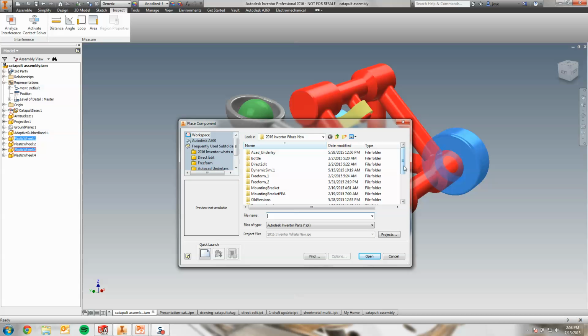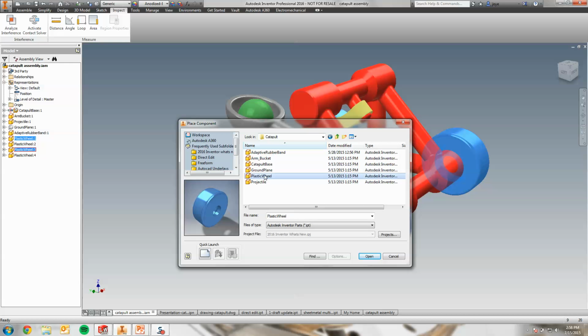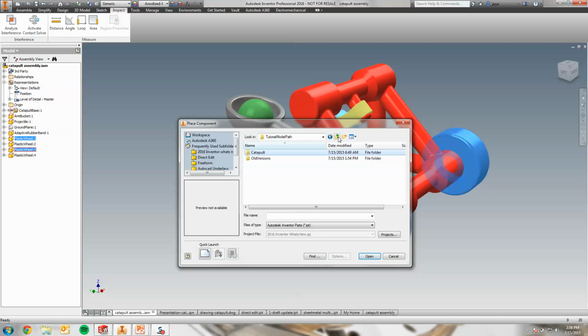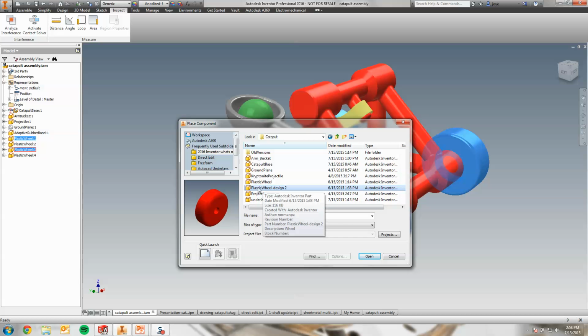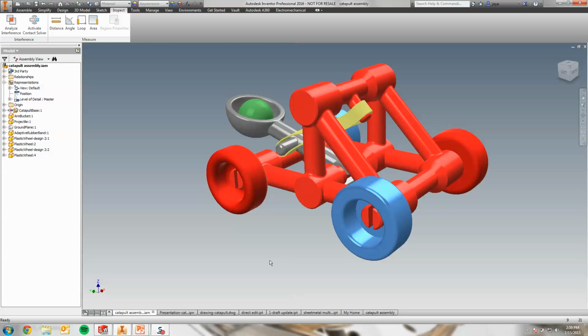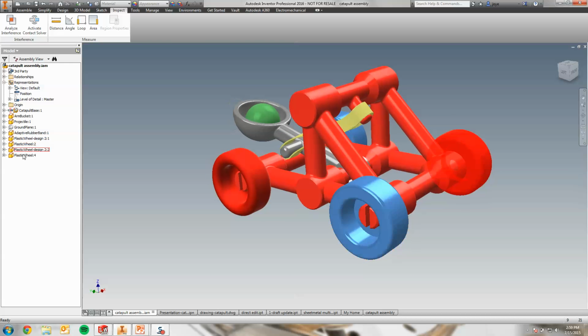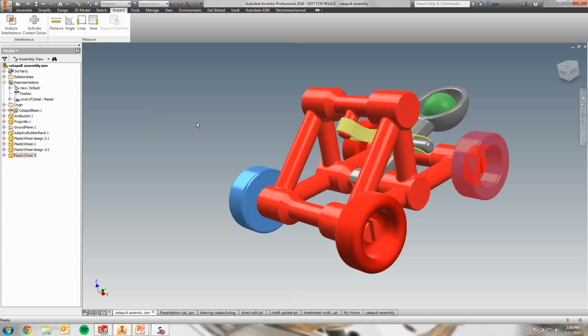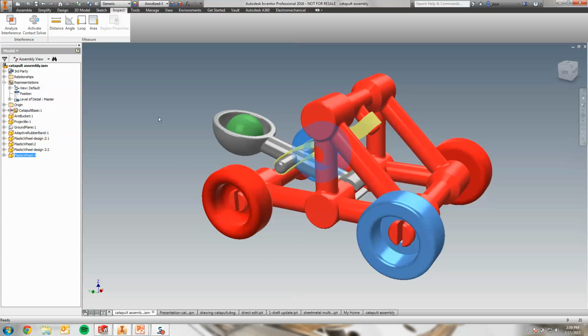Replace, and I could go into, I believe it's dynamic here, let's see here, so here's a different representation of that wheel. So I just want 2 wheels replaced with that instance there. So I just randomly selected 2 components, right clicked, did replace, and I only had to do that one time. I didn't have to right click on each one and do a replace on it.